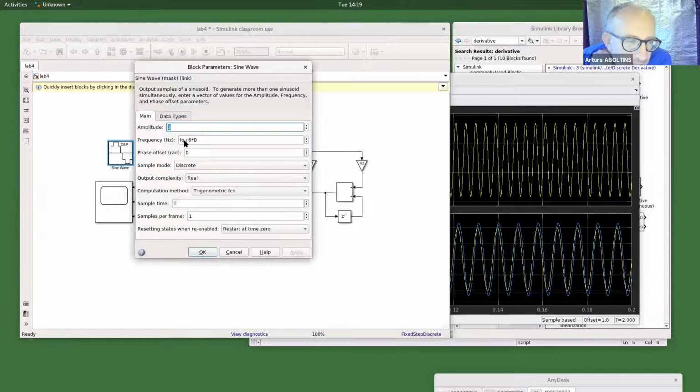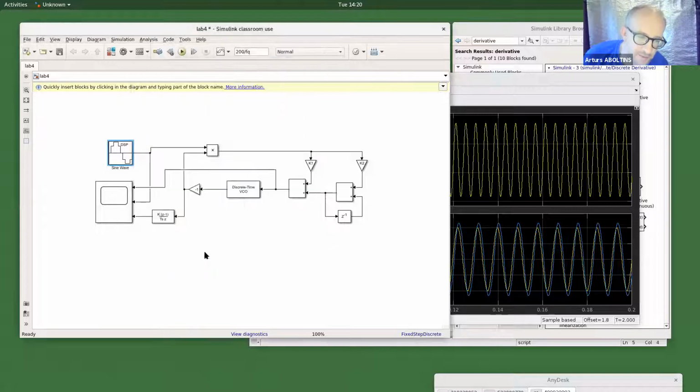Okay, like 5B, maybe it's okay. So it is like 5B, this is a 10 Hertz offset. So that means we could offset because our central frequency is 100 Hertz. Now we can go from 90 Hertz until 110 Hertz in the reference signal, and our PLL will still catch the signal and will be perfectly synchronized to this band of 20 Hertz offset. This is surprisingly big.